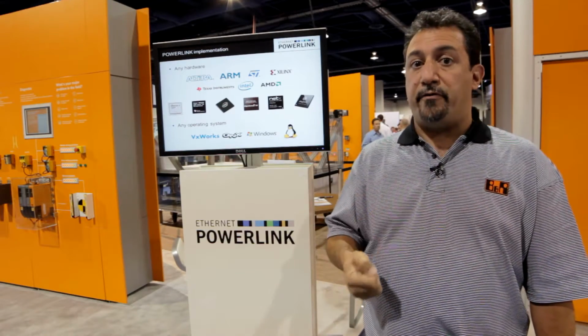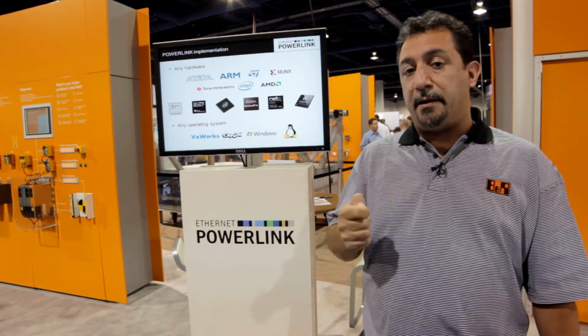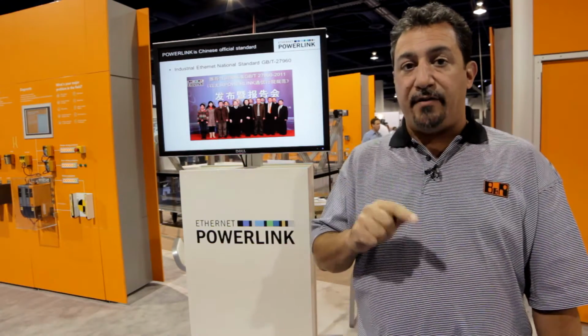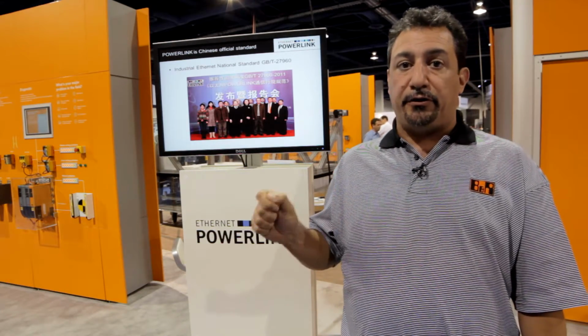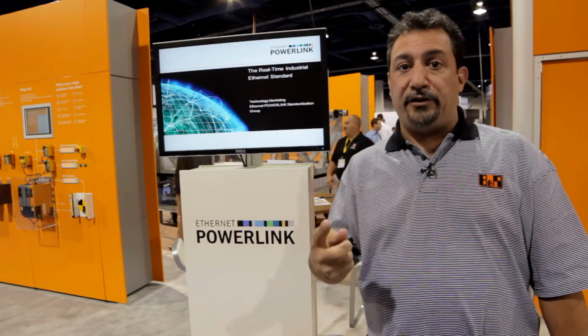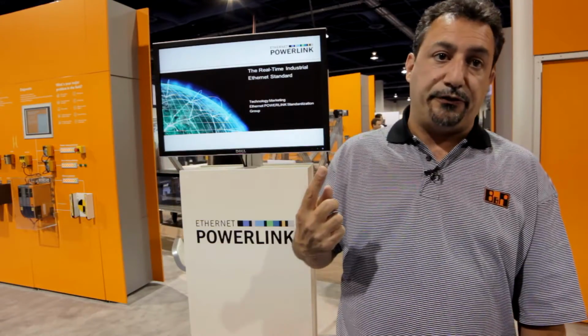The third form of redundancy is master redundancy. Because the POWERLINK master runs the timing of the network, you can have up to 9 other additional redundant masters. So if one of the masters fails, then it'll automatically switch over to the next master with a loss of only one cycle to the system.